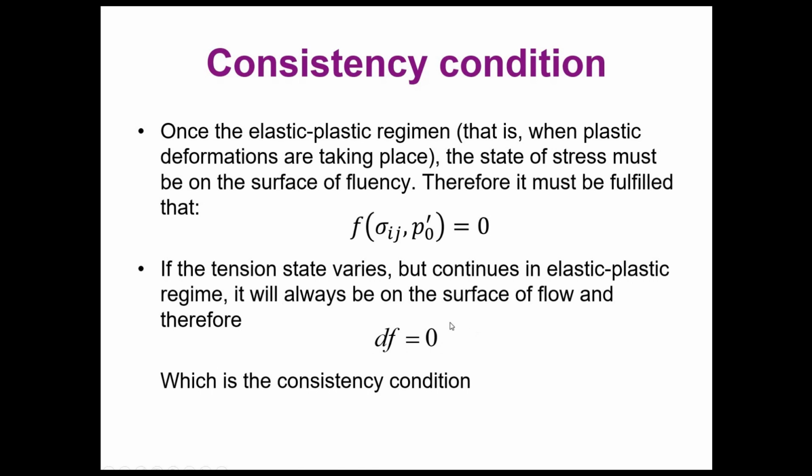Because remember that this surface can be expanded and contracted, it's not trivial, it's not easy to guarantee that you are still on the surface or you went to the elastic regime. So this is the reason why you need this consistency condition to be checked step by step in the resolution of your problem.